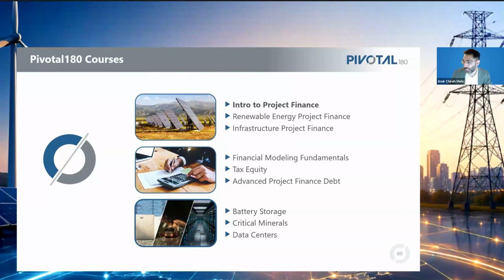To answer your question, Jonathan, where batteries fit in the merit order kind of depends on the price at which they charged. So if they charged at $10 per megawatt hour, in the example I gave you, since they can only sell 80 back to the grid, they need to make at least $12.50 per megawatt hour to break even, because they've lost 20% of their generation just because of the underlying physics. So 10 divided by 0.8 gets you the price: you need $12.50 to break even. That's a really long-winded way of saying it depends on the price at which they charge the batteries and then choose to dispatch into the grid. So it does always follow marginal price, but as a function of those deviations in timing around when they charge, when they choose to dispatch, and so on. I hope that answers your question.